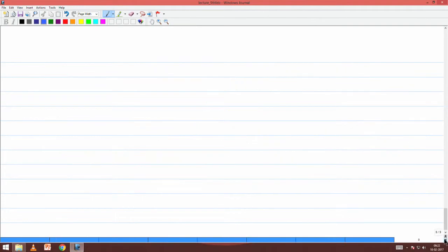So, that is the crucial idea, that it is the shape which matters, the value does not matter in the context of mode shape. And the plot of these mode shapes should be pretty simple to do. We have realized that P x equals sin n pi x by L, right. So, let us look at the first mode shape.